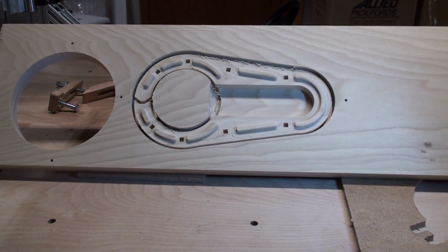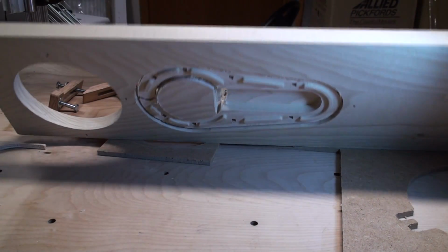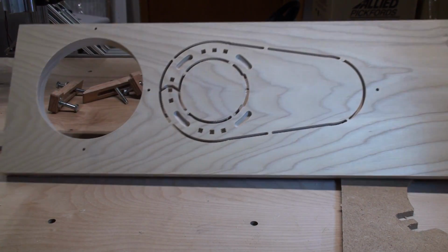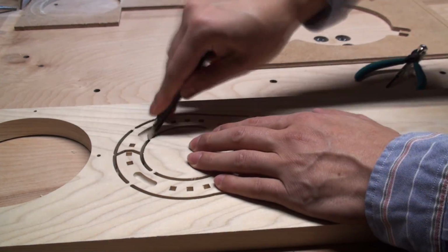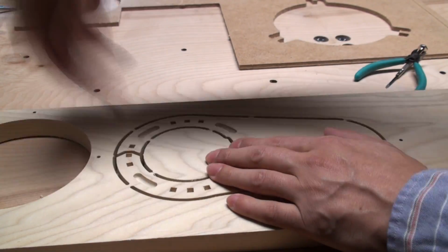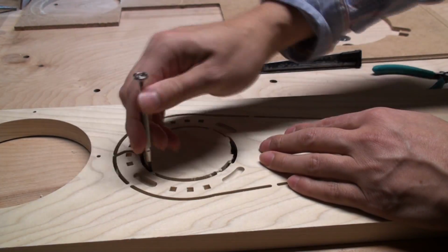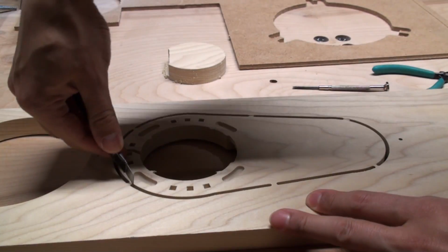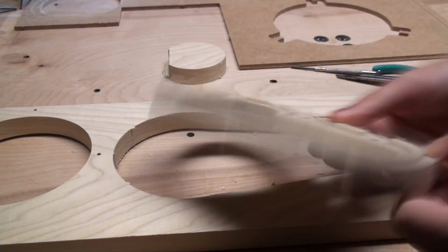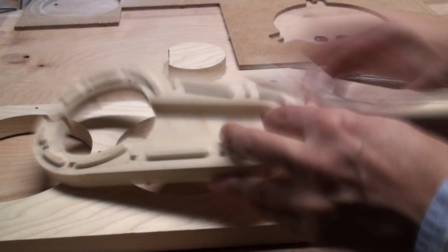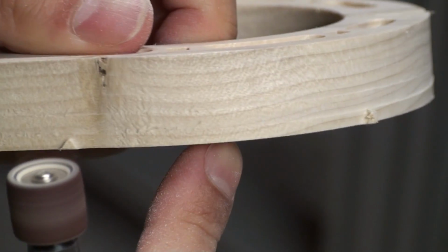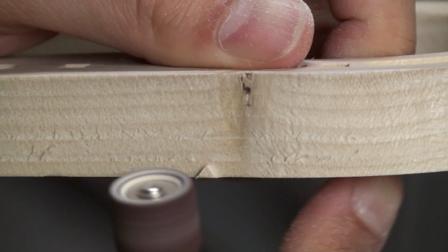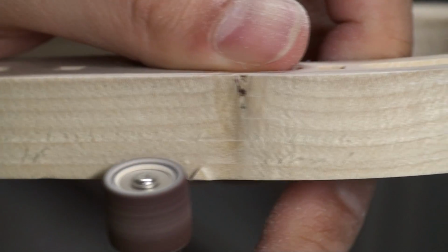So I disconnected the stock from the table, and I'm flipping it over. As you can see, here's the back side already machined, and you can see the tabs which I'm now breaking with the knife. And after the part is taken out of the stock, I give it a light sanding, after which I will use a Dremel tool to take off the tabs. So here you can see the tab with a small triangle, which you can just take off with the Dremel tool.